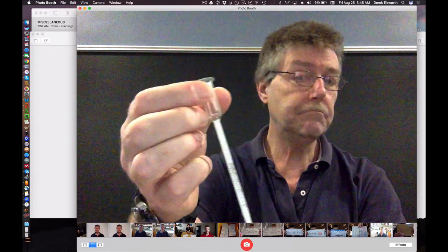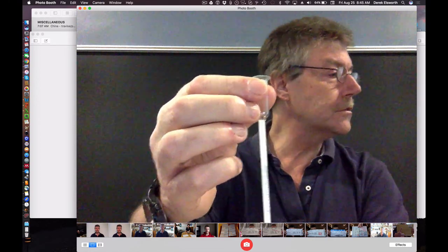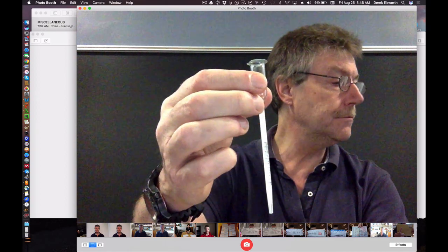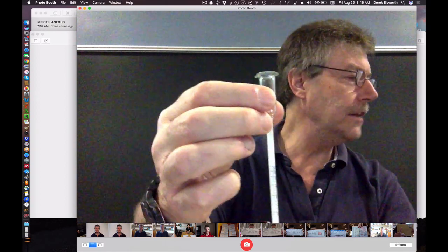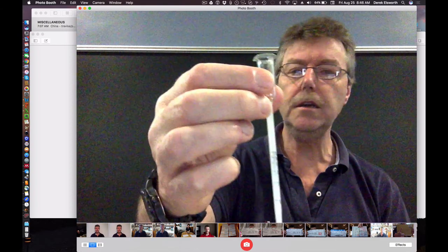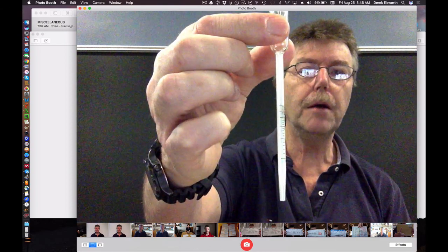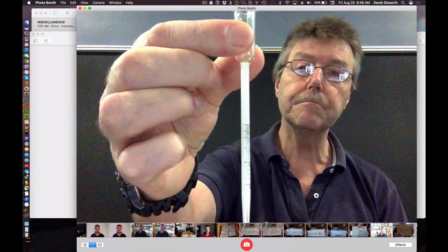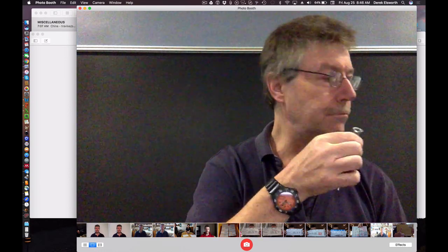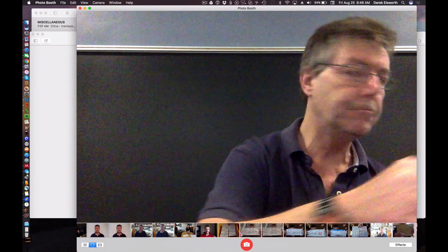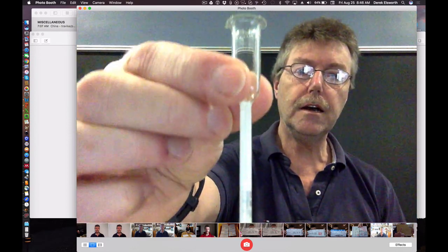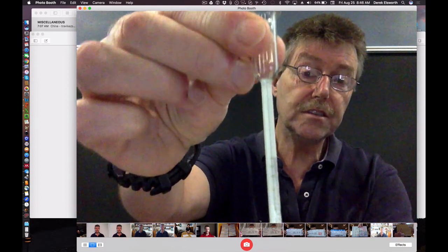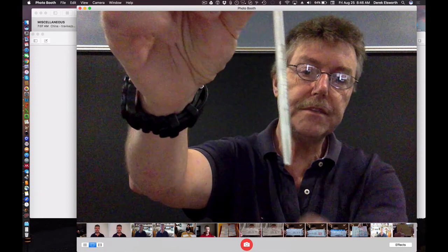The vinometer. So when you're out on Thirsty Thursday and you want to see what the alcohol content is of your beer, or if you're with friends and of course you can't drink because you're still 20, you can put it in a vinometer. A vinometer is just something that gives you the alcohol content of liquids. So what you do is you put the liquid in here. If I had water, I'd put it in. It fills up this little capsule at the top. This is a capillary tube, and you can see the hole through it, which comes out of the bottom.